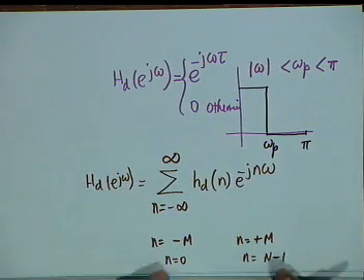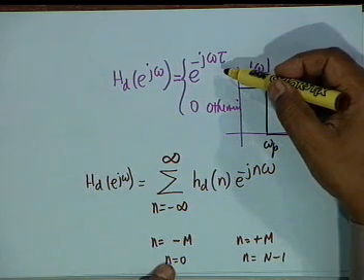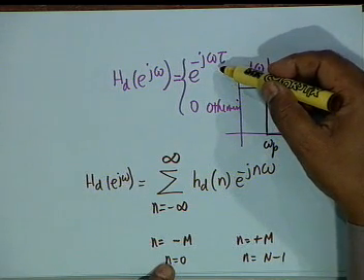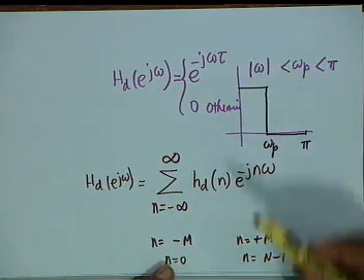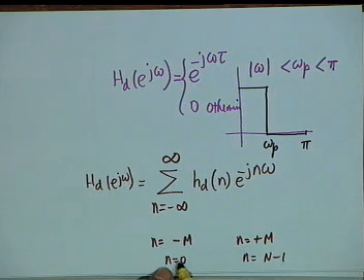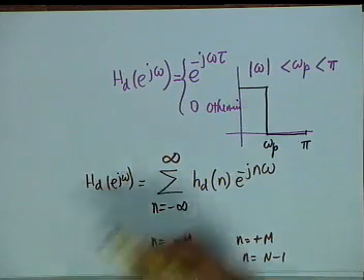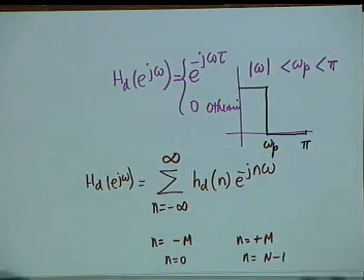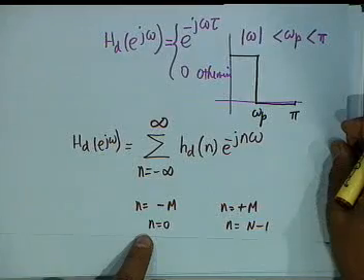Since we have assumed a linear phase, we started from the expansion of a linear phase transfer function, it is guaranteed that the impulse response h_d[n] that we get shall be symmetric or antisymmetric depending on what you want. Okay? You might want e^{j(ωτ plus π/2)}, then it will be antisymmetric, or with a negative sign. Okay? So, there is no realizability problem if we start at n equal to 0, and therefore, this is what we use.